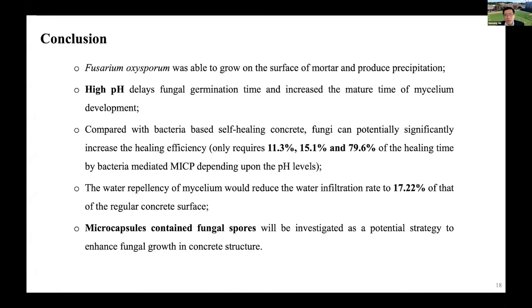So in that case, do you think the hollow structure will be beneficial? I mean, having some sort of side benefits like improving durability, for instance, resistance to freeze-thaw or to alkali-silica reactivity, because they provide additional space to buffer the tensile stress potentially. Yeah, that's a good point.